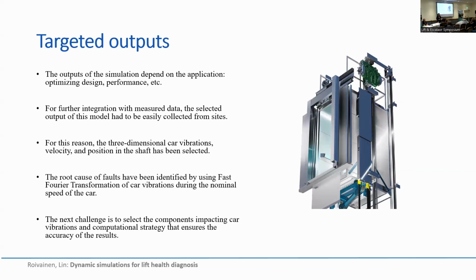Then for identifying the root cause of the faults, we were using fast Fourier transformation. So we were using spectrums and spectrograms of car vibration during the nominal speed of the car. We are not interested in acceleration, deceleration. We target the nominal speed of the car, and we try to identify which source is behind which frequency that we see in the spectrum.